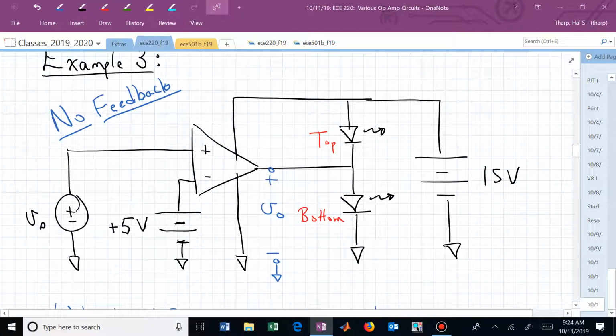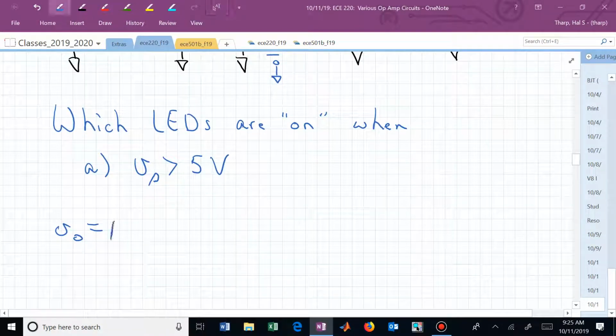What is V0 in an op amp? What's it related to? Be thinking about one of the first figures with this operating region, where we had the linear operating region and saturation on the low side and the high side. What was the linear operating region functional form? What was the horizontal axis in that figure? That was the difference between the non-inverting input pin's voltage and the inverting input pin's voltage, V sub p minus V sub n. V sub O, or the output voltage, was A times (V sub p minus V sub n).